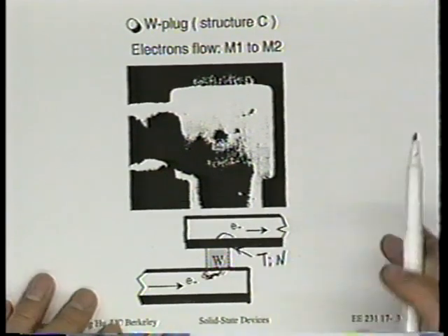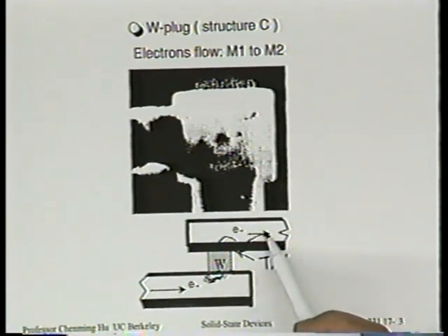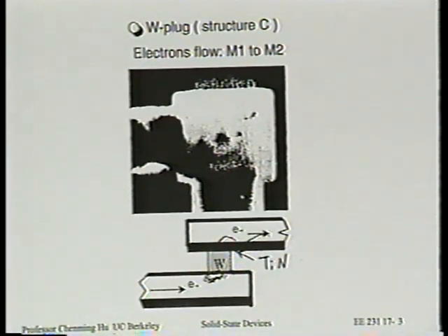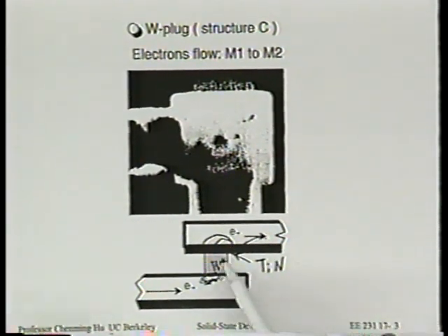All right? So in that case, actually a thicker titanium nitride on the bottom of metal 2 would be desirable. So in this case, current actually can still flow through titanium nitride for a while before going into aluminum. You see that? So first of all, it avoids this positive feedback, creating a really bad void, and also even if this whole part is covered by a void, you won't get an open circuit. Is that right?